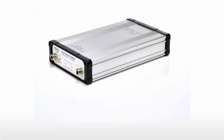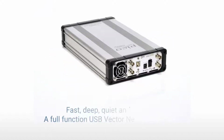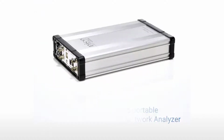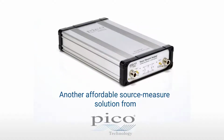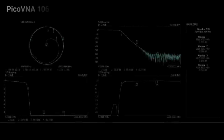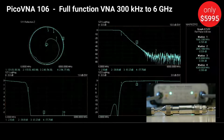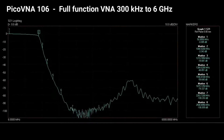Hi, I'm Mark Ashcroft. Let's take a quick run through some of the features and performance of the PicoVNA 106 USB-controlled 6 GHz vector network analyzer. Fast, deep, quiet and portable, the PicoVNA 106, despite its small footprint and its low price, is a full-function 2-port bidirectional VNA, with all the measurement and plot formats that you would expect, and of course, the PC and monitor of your choice. There's nothing left out here. Nominal impedance conversion to 75 ohm, for instance, reference plane shift and embed de-embed are all included.